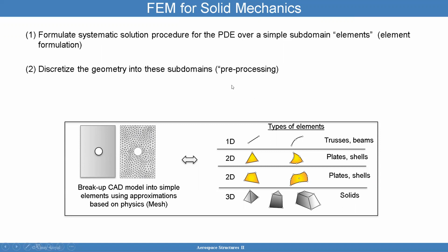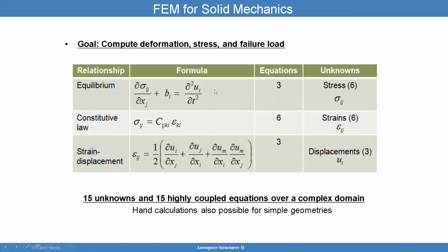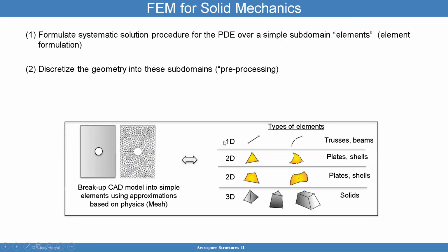And that element is where you do all the calculations. The cool news is that you can take these 15 equations, 15 unknowns, and formulate and solve them for that standard element. Once you have that standard element formulated, you can map it back into these irregular elements, because every single triangle here is not the same as that standard element.